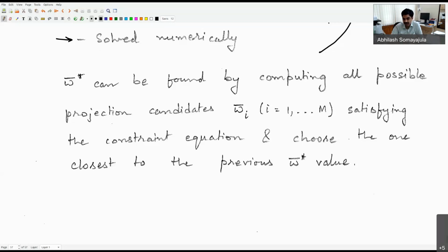If we choose R too small, that methodology does not work. Whereas the look-ahead distance based LOS scheme always works no matter what the situation is, so that is a better approach. No wonder it was the more popular approach for missiles, and it has become the norm nowadays. You don't see much happening with enclosure based LOS anymore.